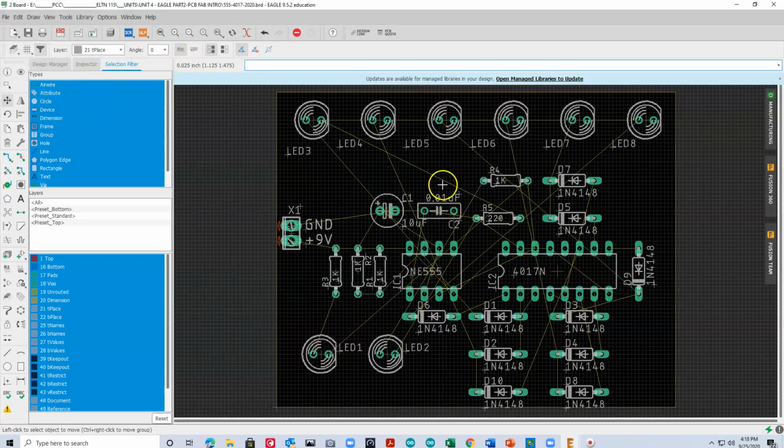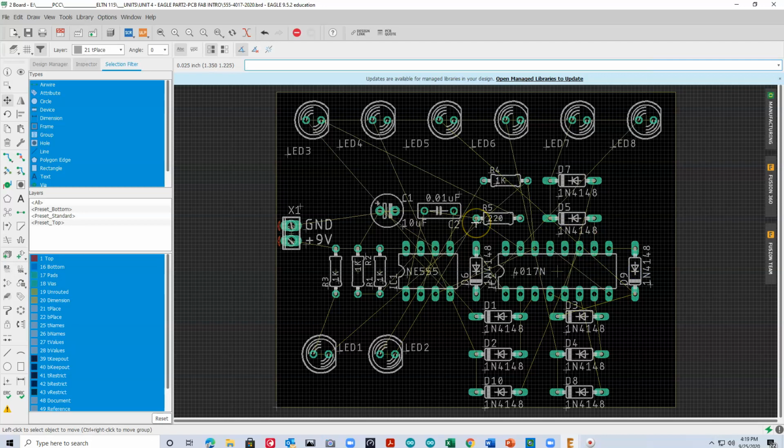Okay, so our circuit's looking pretty good here. It's not perfect. I'd probably make some changes. I might, for example, move this diode over to here to make it a little more consistent with the diode on the right, but it's kind of aesthetics at this point. Now, the next thing we want to do is figure out if we're going to mount this in some kind of enclosure or box. We'd typically have what are called standoffs that we mount the boards with. Those are basically either aluminum or plastic spacers, typically anywhere from 1/8 of an inch to 1/4 inch to 1/2 inch long.